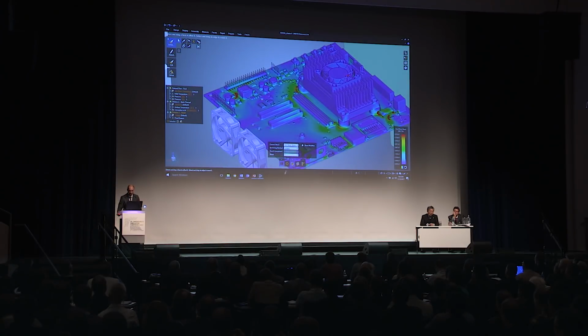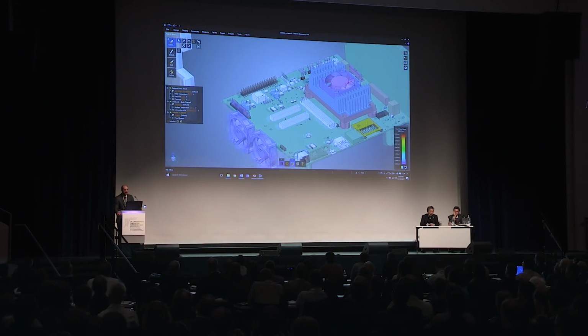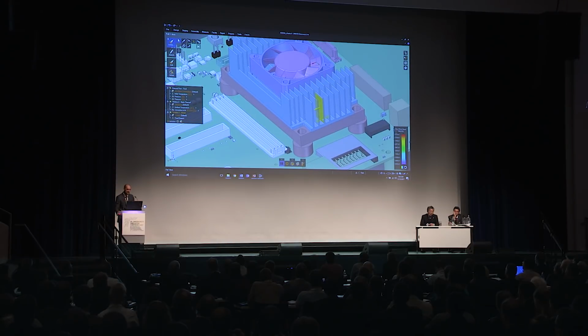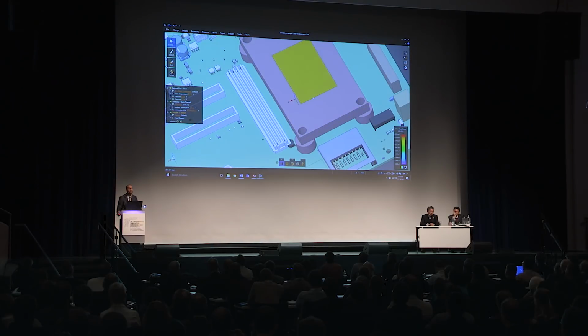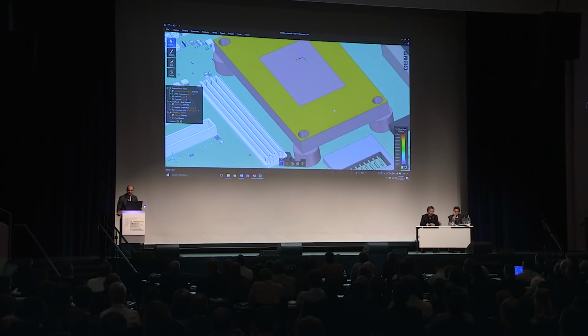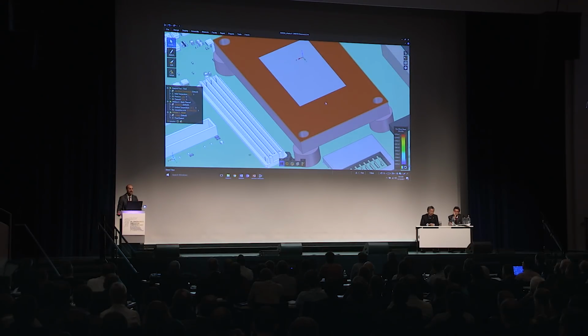But let's do more. Another key element of this design is this big heatsink. NVIDIA put this whole big metal heatsink, and to me it looks fairly simple. So I wonder if we can do better. Let's delete theirs and create one of our own. To do this, let's take maybe these faces that appear here and make a copy of them. And oh, by the way, I want my heatsink to be blue. It's my favorite color, so we'll go with that.